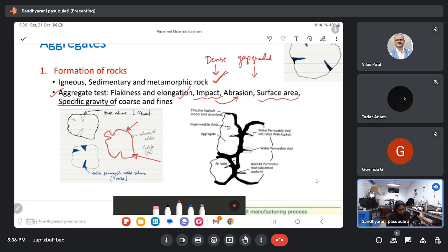So if I consider that, it is called the apparent volume. So the specific gravity we calculate would be the apparent specific gravity. But take that we want to consider this entire total volume, that means the voids that are present, we also want to include. That means this is volume V2. Specific gravity is weight by volume, so when V2 is more, G will be less. That is the reason why bulk specific gravity will be less and apparent will be more.